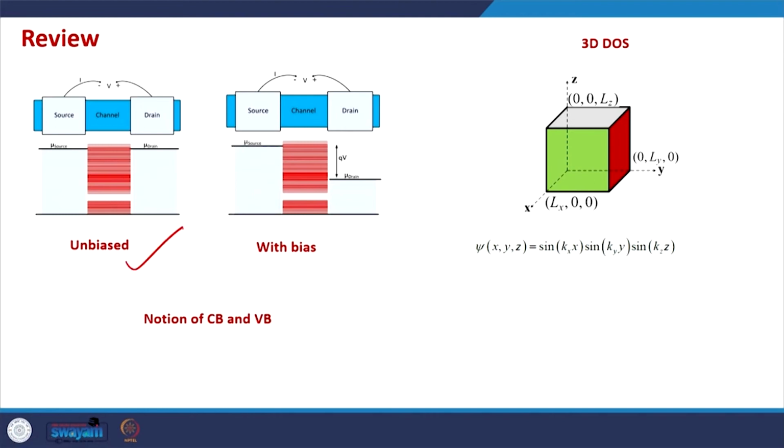This is an unbiased two terminal device. With bias, the source and drain Fermi levels change. Just a short note, Fermi level is represented as EF or mu. Generally this notation, mu, is used mostly by physical chemists, people in chemistry. This notation, EF, is mostly used by solid state physicists.